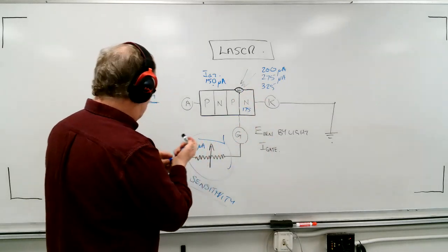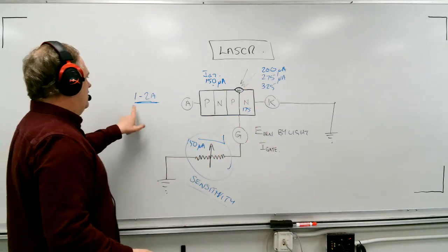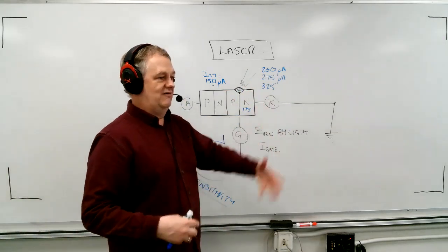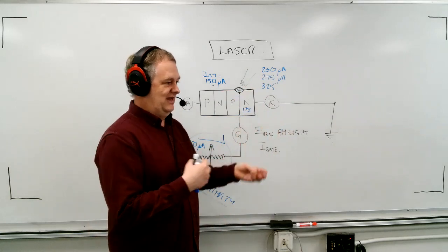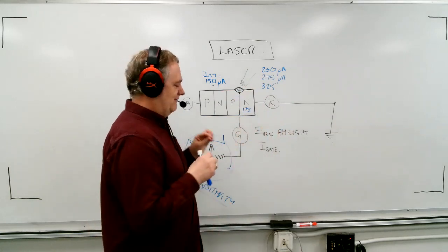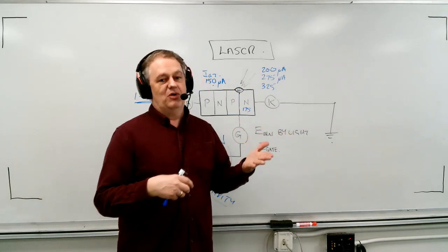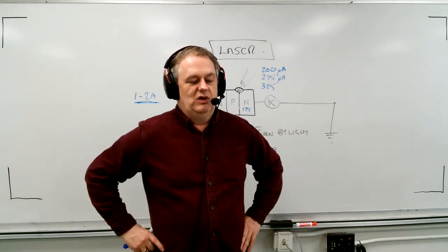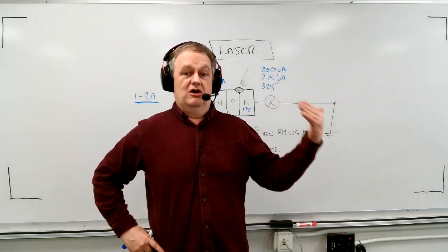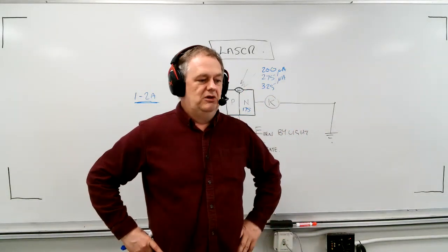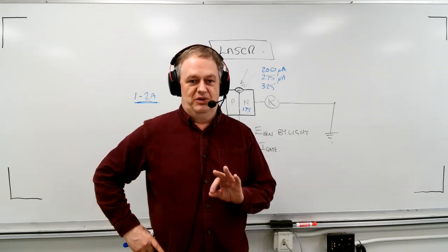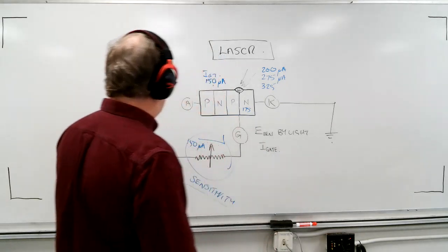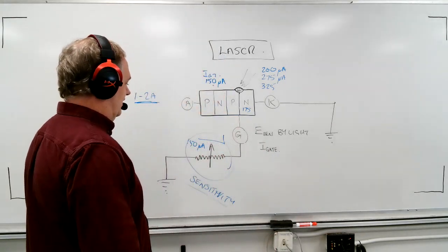So quite an interesting device. Like I said, normally quite low currents. If you need it to operate much higher values of current, then you'll cascade them, we always say cascade them. You'll take a very, very small SCR, maybe operate a larger SCR, and then a relay. So there's many ways of doing whatever you need to do to get the current capability that you need. But in terms of the actual component and how it works, this is really neat. And that's the active component in photocells.